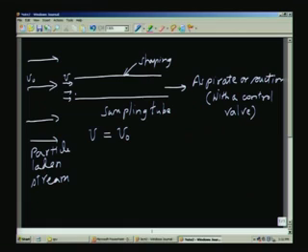The velocity in the tube will be monitored, and the aspiration rate and the suction rate will be adjusted such that velocity is equal to u naught. So, this is one part. The second part is that we have to have tau, the Stokes parameter, less than 0.01. These are the two things.